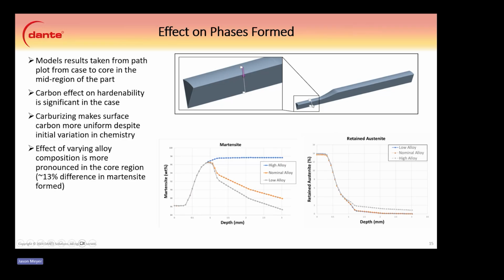So this one used tensile samples, so we used a little bit of an eighth geometry here. We halved it via symmetry, and then we quartered it to reduce computational time. And we can see the difference here with the phases with this path plot. We can see we have about 86 or so percent martensite where the carbon is high here. The rest of the balance here is retained austenite. This was not tempered. This was just as-quenched condition, if I recall correctly.